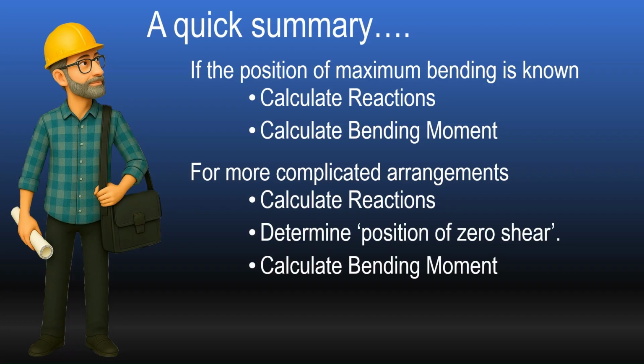So you calculate the reactions, you then determine your position of zero shear, so you clearly need to understand what shear forces are, and then you can calculate your bending moment at that point. And that's it really. Even in more complicated scenarios, assuming that your situation is statically determinate, then you follow exactly the same process.